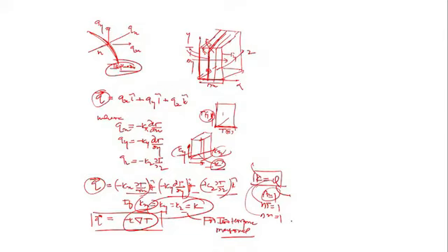In the modern view of material, the solid may be comprised of free electrons and atoms bound in periodic arrangements, that is called a lattice. So there are free electrons and a lattice. Lattice means periodic arrangements of atoms or molecules. According to transport of thermal energy, the thermal energy may be transported due to the following two effects. One is the migration or translational motion of free electrons, and the other is lattice vibration waves.